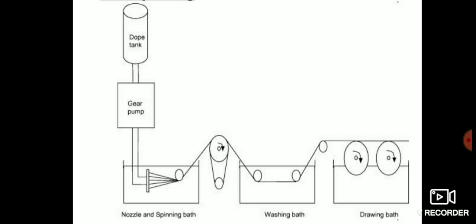polymer. The rate at which this occurs is crucial, as if it occurs too quickly, the bath liquid can create micro voids in the fiber, which will be a weak point. Wet spinning is based on precipitation, where a polymer is drawn through a wet spinner or spinneret into a non-solvent. The prepared spinning dope is extruded into the non-solvent and precipitation or coagulation occurs.